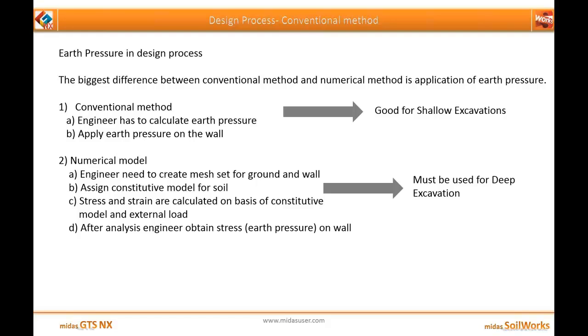But in the numerical model, the engineer needs to create the mesh for ground and wall, then define their properties by various constitutive models. Then the stress and strain are calculated on the basis of the constitutive model, and after analysis the engineer obtains the stress, or the earth pressure, which is going to act on the wall. So this type of numerical approach becomes very important for deep excavations.